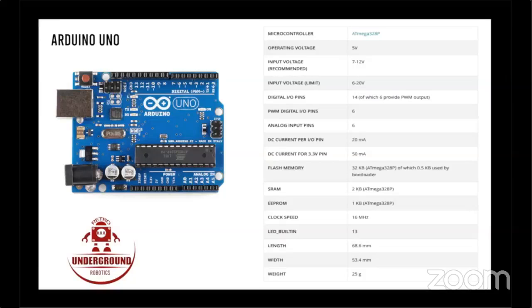You need to know what the operating voltage is, right? Is it okay for the input voltage to be 3? Is 3 volts fine? What about 19? What about 12 and a half volts or 13 volts? Am I good there? And what happens if for some reason we get 25 volts into the Arduino?